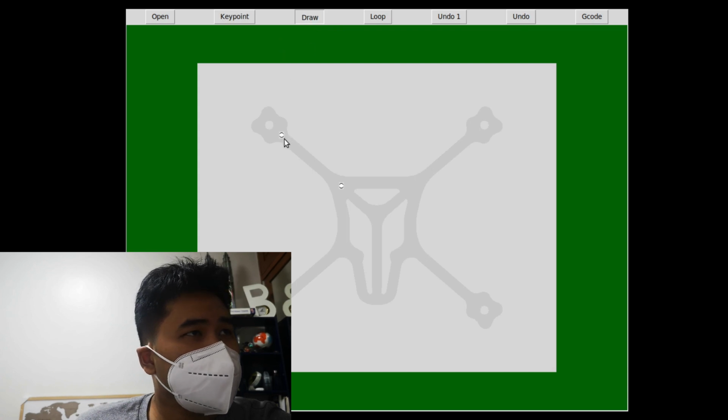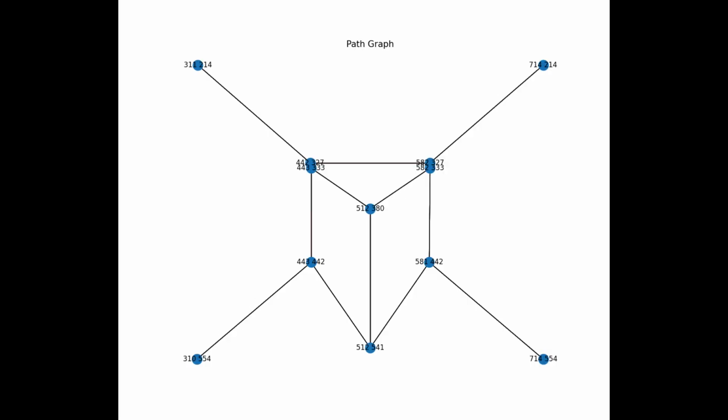Like everything, we can do this manually. But where is the fun in that? So let's try to automate the process. First, we project our 3D object into a 2D image for easier analysis. Once we have this image, we use a thinning algorithm to generate a possible path for our target objects. From these points, we can generate key points from the intersection of the lines and use that as nodes in our graph. Then, we only need to traverse the edges, and now we know our path.